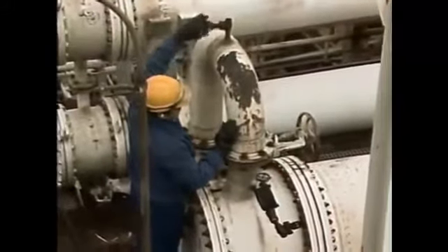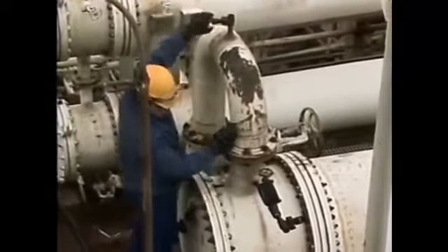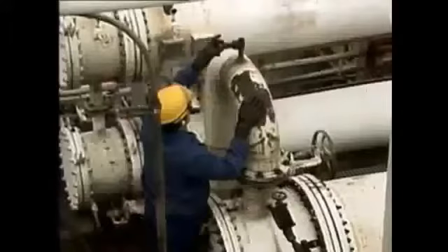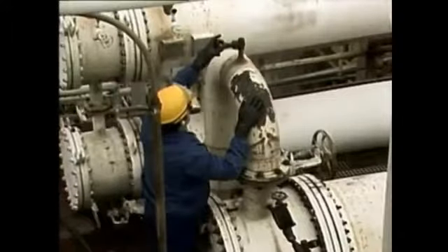With the valve checks completed, the operator opens the vent valve on the tube side of the condenser. Then he partially opens the cooling water inlet valve. The sound of escaping air means that cooling water is filling the tube side of the condenser. When the tube side is filled, a stream of water flows from the vent. Then the operator closes the tube side vent valve.